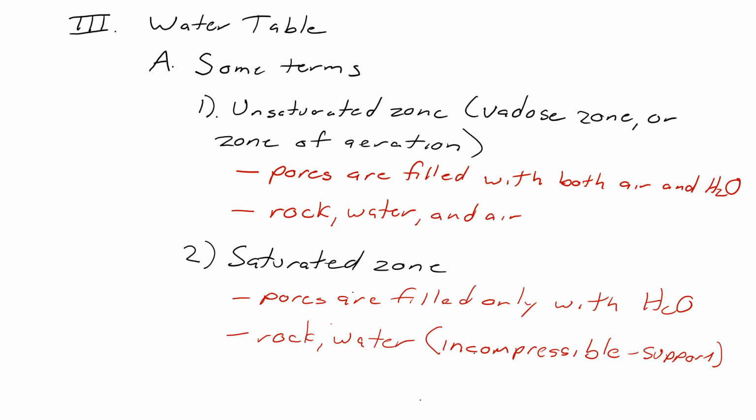So you may have had a situation where you had a nice porous and permeable rock, and then by pumping too much and sucking too much of the water out, replacing it with air, those pores can collapse, the porosity reduces, the permeability reduces, and you can go from a nice, functioning aquifer to a rock unit that won't give you any water at all. And that is a problem that is occurring in many parts of the United States today.